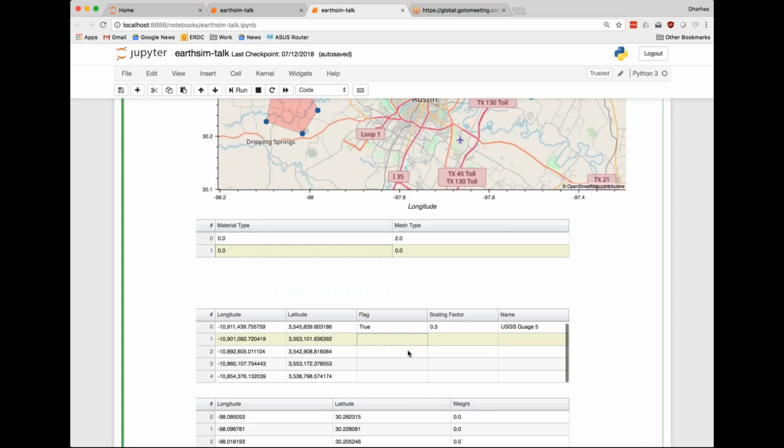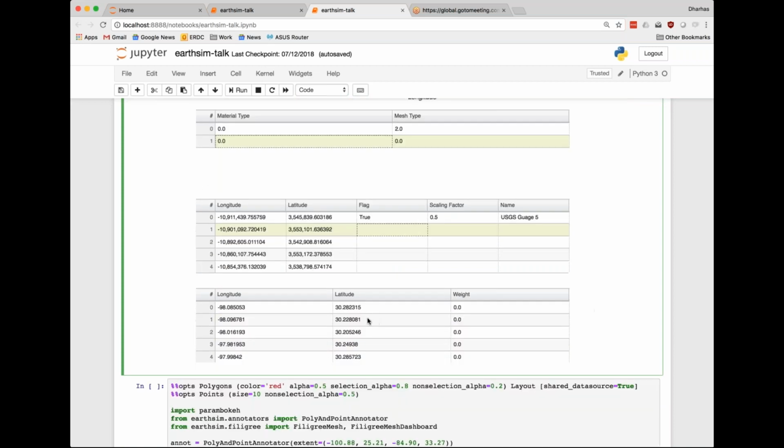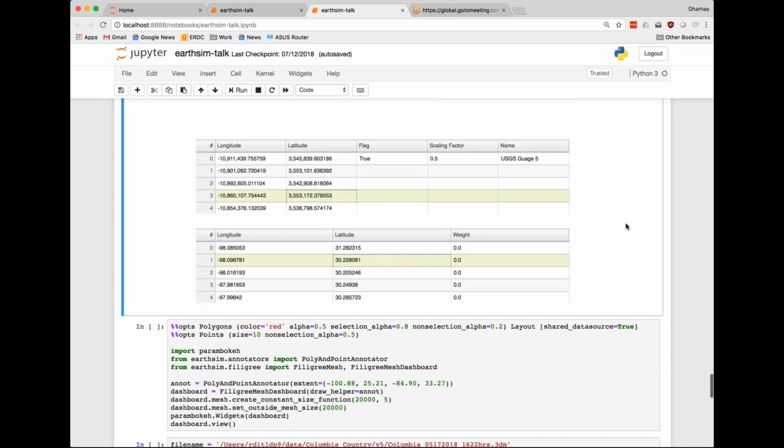Yeah, like if you look down here, this one actually shows you in latitude, longitude. And yeah, so it's more a case of the way I set it up was slightly wrong. So this one is in latitude, longitude. I can change this to 31. The other one wasn't. And that's probably just because I forgot to set the coordinate system in that code for this cell. Okay.